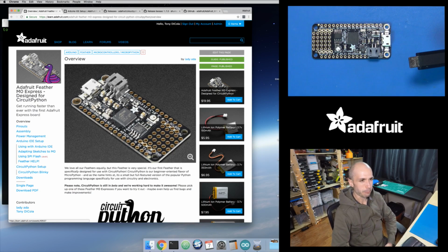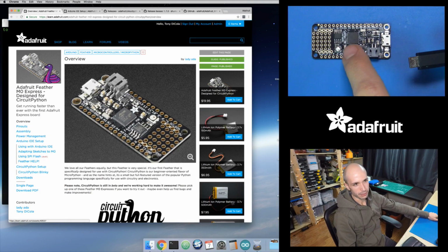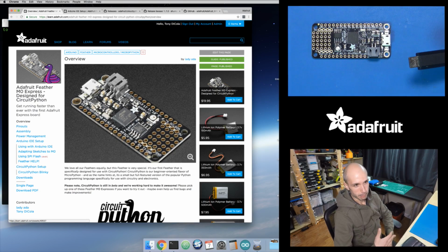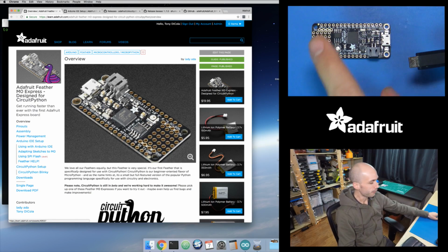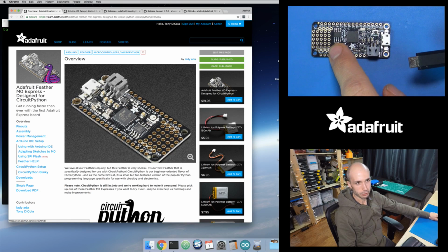And actually, I think we have a little SPI chip in the shop now that I'm thinking about it that uses a breadboard compatible interface. So you could build your own, but the tricky thing though is that these processors aren't meant to run their code off of that flash chip. It's more for getting data off of that flash chip, and that data might be a Python file that's then loaded in memory and run with CircuitPython. So that's the big standout feature for the Express boards, is the addition of that flash memory, which will give you more space for program code, and then more space for your Python code also that you're putting on here.